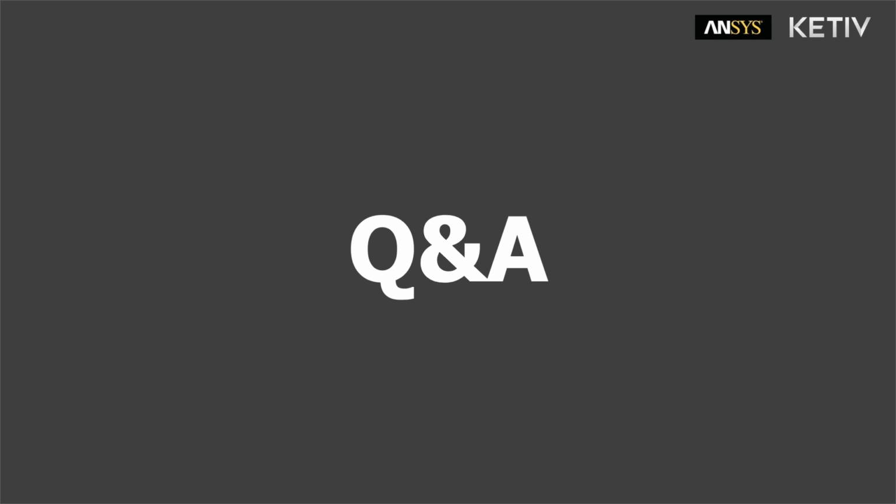I would say that. Go ahead, Eric. Oh, sorry, I thought you were done. I'd just like to add that with the other ANSYS products, our flagship products, you can really reach any arbitrary level of accuracy if you're going to put in the time and the computing resources. With Discovery Live, there's sort of a maximum which is limited by your GPU. So if you have a good GPU, you can get more accuracy out of it. If your GPU is a little weaker, you're going to be more limited.